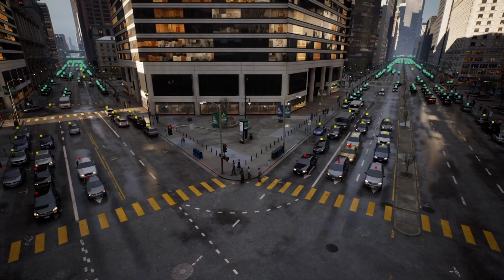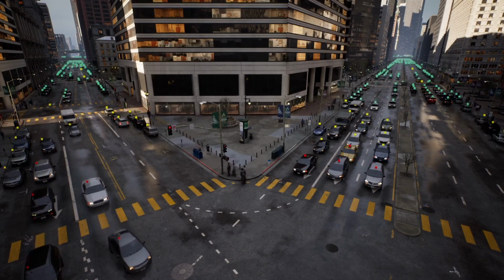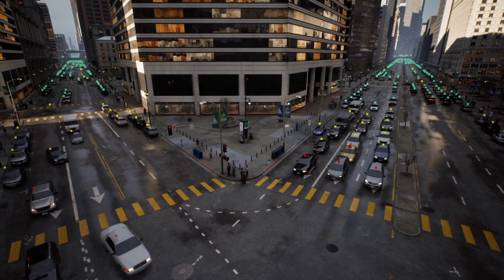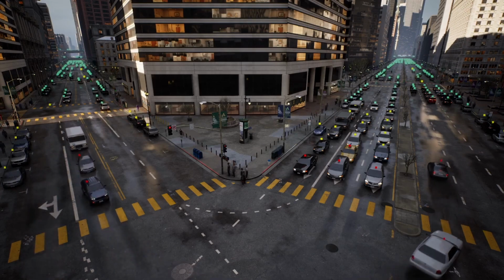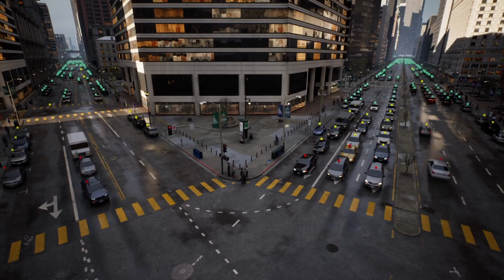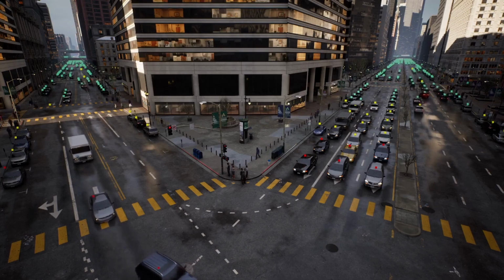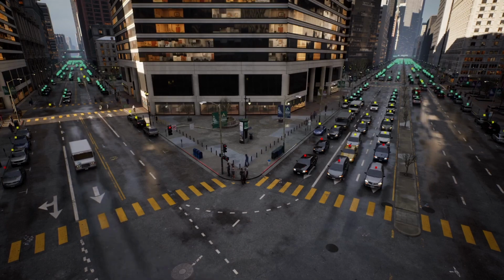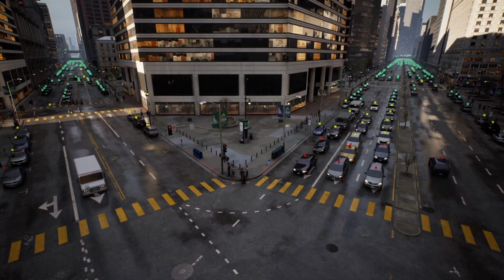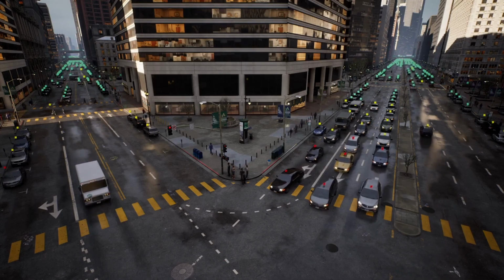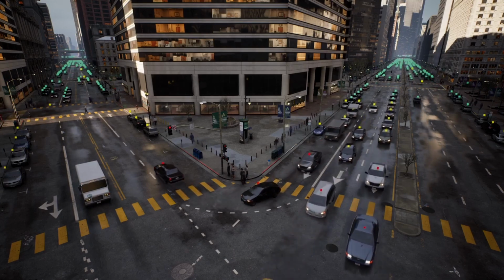There are a total of 17,000 traffic vehicles and 38,000 parked but drivable vehicles. On the screen we can see in red 10 LOD 0, fully simulated physics vehicle actors that can be deformed, destroyed, and interacted with. In yellow, up to 150 medium LOD that are still running physics but with simpler suspension and all simulated within the Mass framework. In green, up to 5,000 low LOD, which are instanced static meshes following simple curves and position updates. The rest are not visualized.